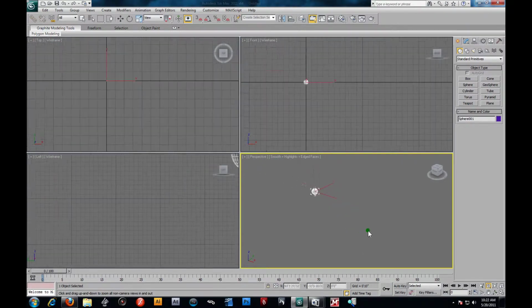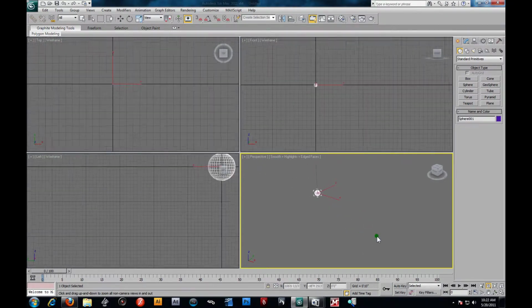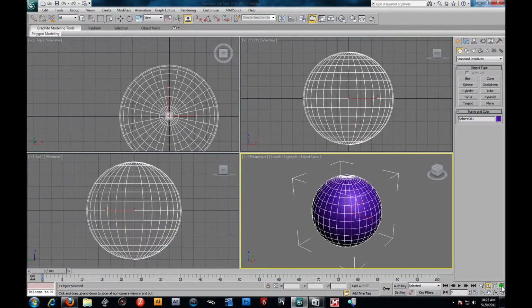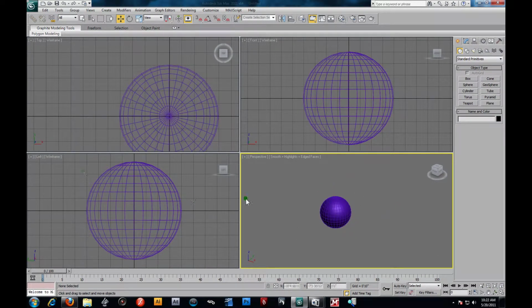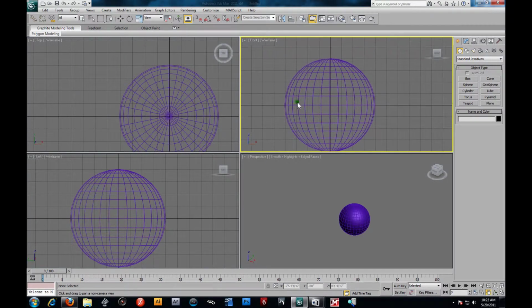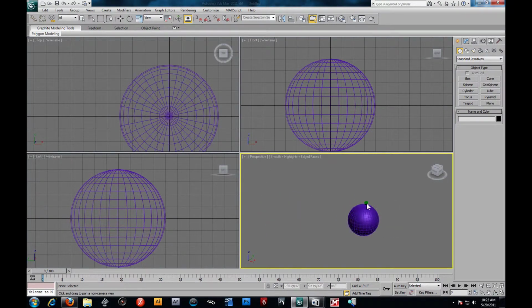That was kind of a bad example. What I was trying to get at was, I forgot, you have zoom extents. You can click that, and that will zoom everything back up into place. I'll explain that a little bit more. Also, you have your pan tool, which is your hand, so you can pan back and forth. Your hotkey for that would technically just be your middle mouse, so you can hold it down and pan.